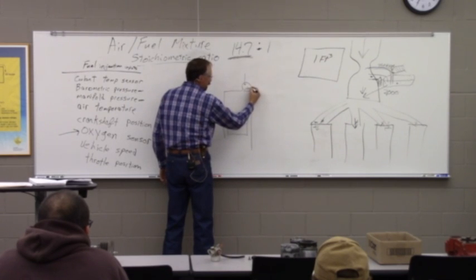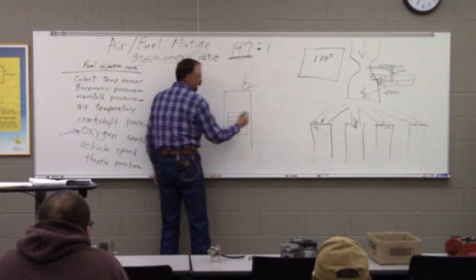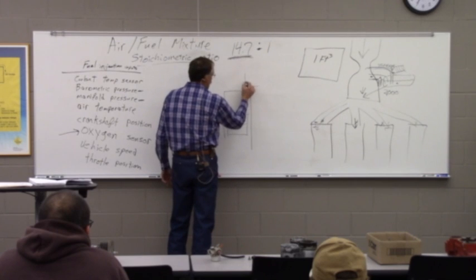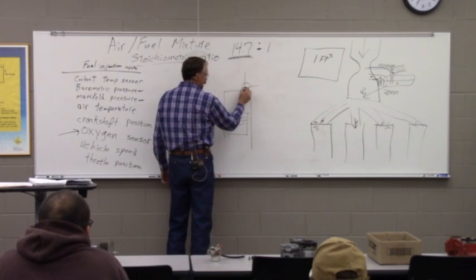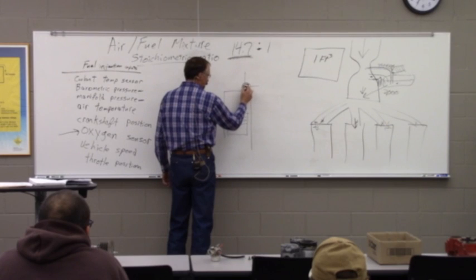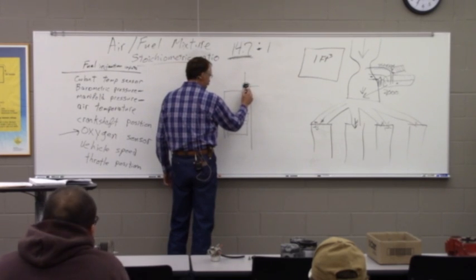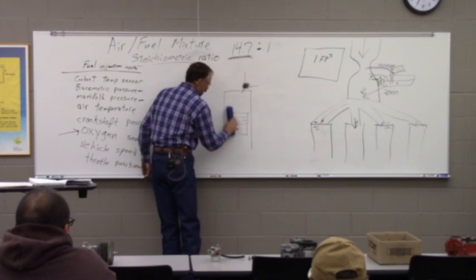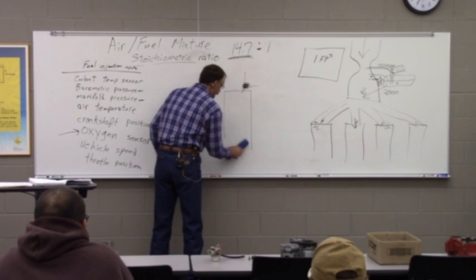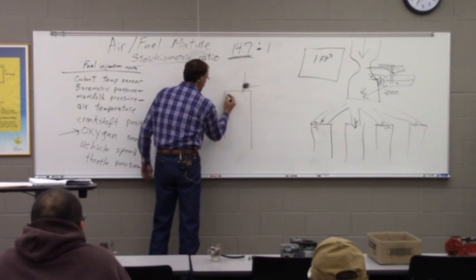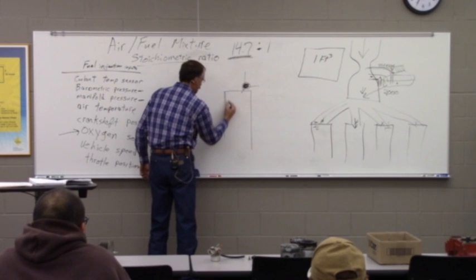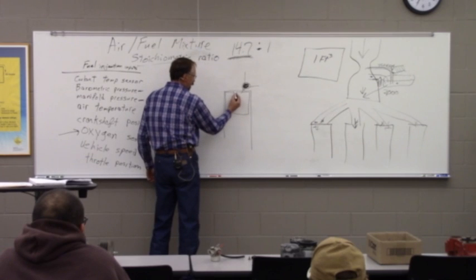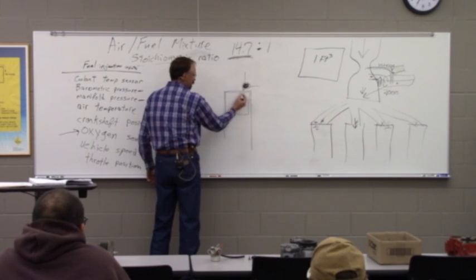And in many of those engines, the glow plug that was used for extra heat on startup was also in that pre-combustion chamber. They would squirt the fuel in there and get it all swirling and vaporizing and get that combustion started, and then it would come out here. Now, I probably didn't do the best job of drawing that, because when that happens, the piston, again, we're talking high compression engines, 18-to-1 or something like that, is up here where there's very little space.